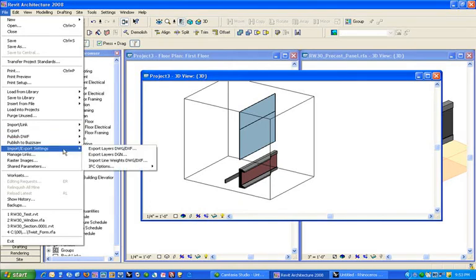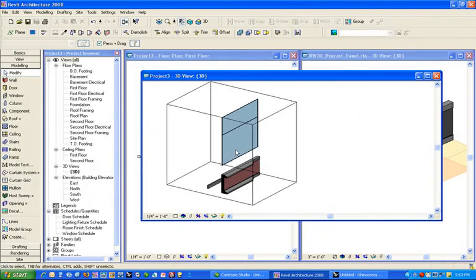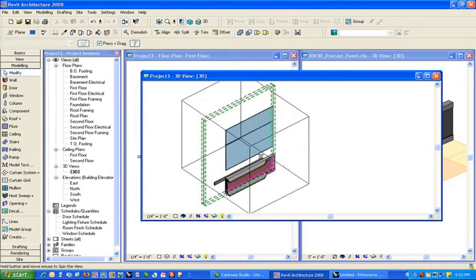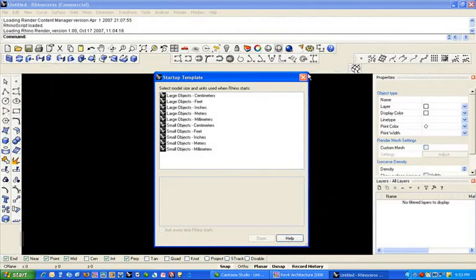And then you can save some of your export settings for IFC. The IFC geometry engine is built on STEP, which is a really good, solid NURBS geometry. But the problem is you can't export it as a STEP file. It's only an IFC file. So certain software imports IFC files, but not that many. Ecotech analysis, an inexpensive, good analysis software, imports IFC files. So that was your BIM dork session.